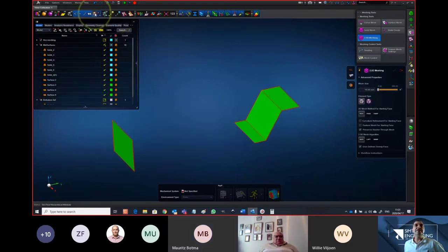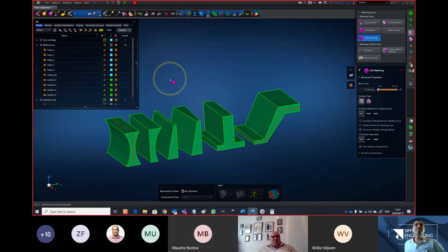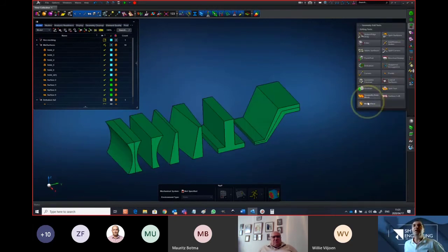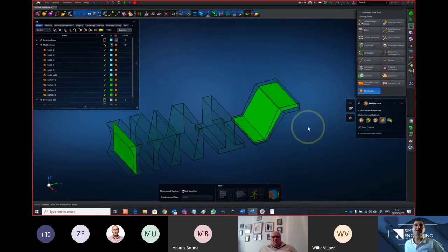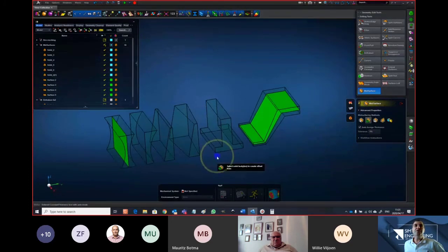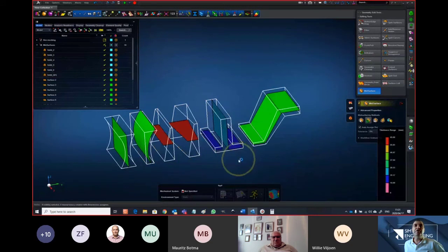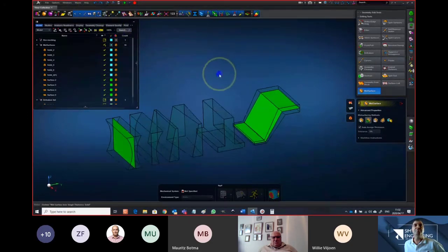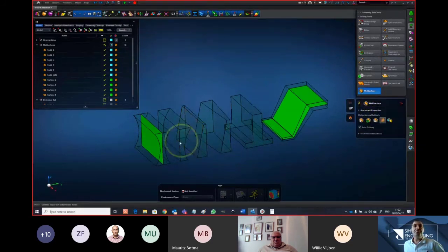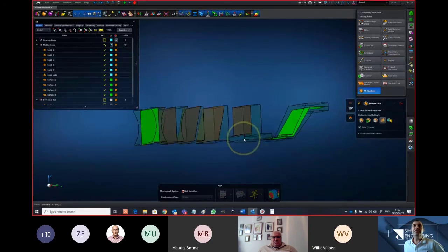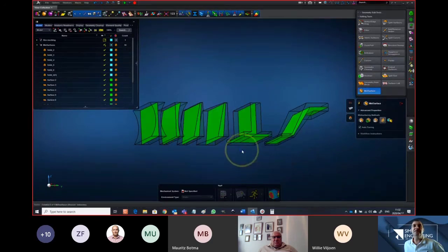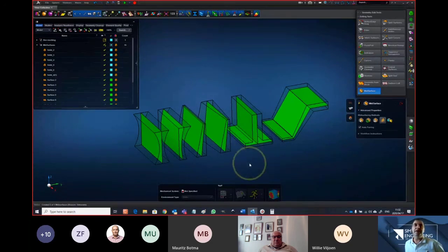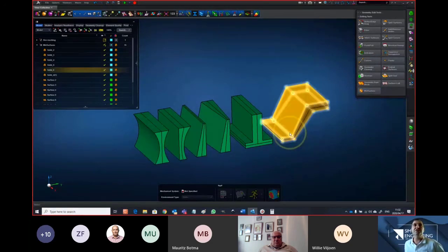Understand. Okay, perfect. That's a good question. So with irregular bodies like these, the only mid-surfacing tool that assigns the thicknesses automatically is this one. What we saw in this case was that these bodies didn't mid-surface very well with this functionality. Although it assigned a thickness, that was not the mid-surfaces that we were interested in. Okay, so that body is not suitable. But using the other tool, we can still generate the mid-surfaces and assign the thicknesses automatically, although it's just one additional step.